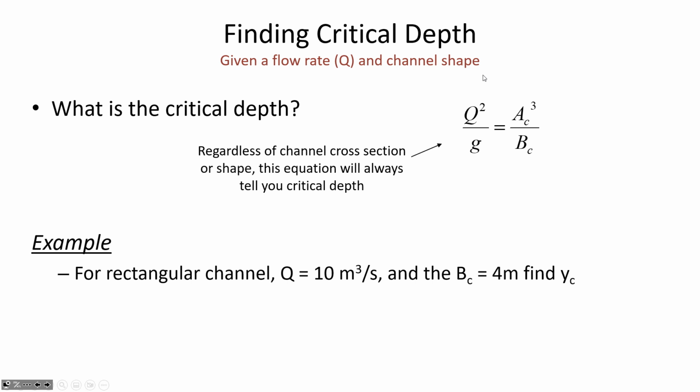and now let's substitute in the flow rate. The flow rate is 10, so it's 4 times 10 times 10, because it's Q squared, so 100 on the left-hand side. And we're taking that to the 1/3 power divided by 9.81, and then that is going to be equal to y sub c.